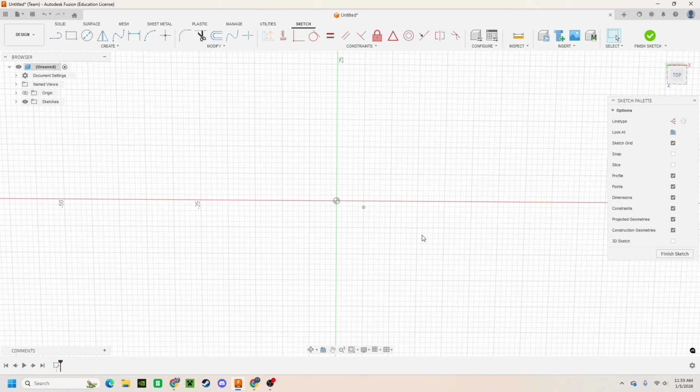The next constraint we are going to look at is the coincident constraint. We have also used this before, likely without knowing. Coincident essentially forces two objects to be connected to each other. If you create a straight line started on the origin, you will create a coincident constraint. This is where the endpoint of the line is coincident to the origin. If you click on the origin, you will see this symbol pop up. This means that it is coincident, and this means that that endpoint will always be connected to the origin. So that can constrain the position of this line.